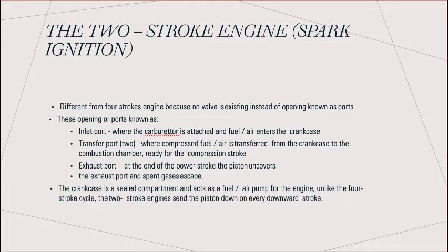The first opening is known as the inlet port, where the carburetor is attached and the fuel and air enter into the crankcase, and the transfer port, which is number 2, where the compressed fuel and air are transferred from the crankcase to the combustion chamber, ready for the compression stroke. And the third is the exhaust port, where at the end of the power stroke, the piston uncovers the exhaust port and spent gas escapes. And the crankcase is a sealed compartment and acts as a fuel and air pump for the engine.